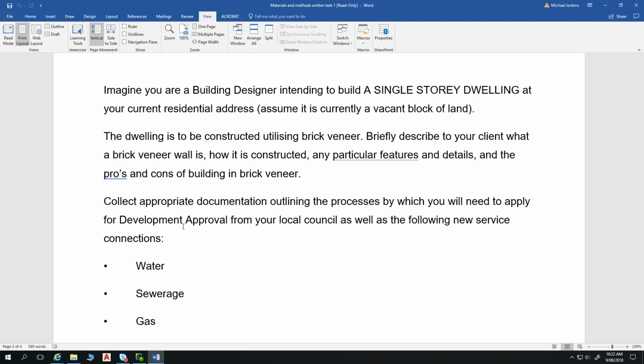We also, when we design brick veneer, we accept that water will get in there, because water gets into places, and it's an important thing that we ensure that water gets out of there. And so to enable that, we have flashings built into certain sections as well. So that's just an embossed polythene, like a plastic membrane that's fairly rigid, nailed back to our stud and carried under our brickwork, and that X denotes a weep hole in a vertical sense.